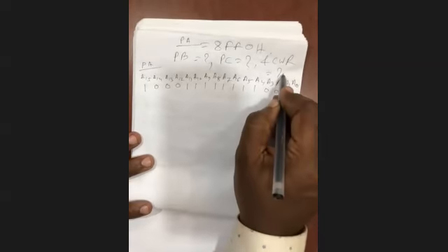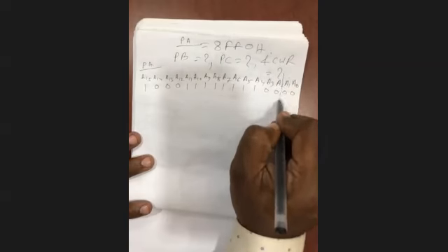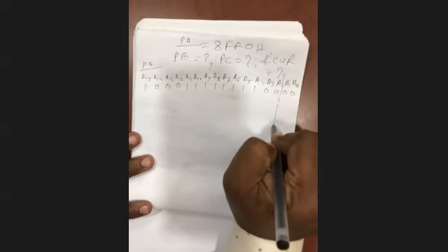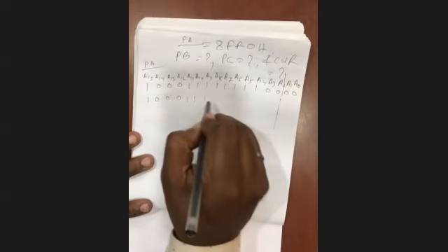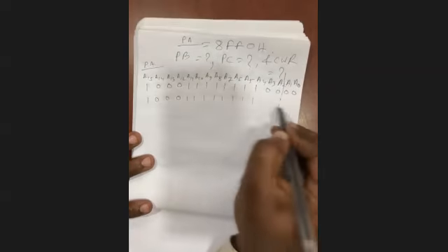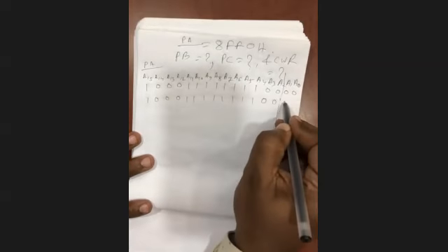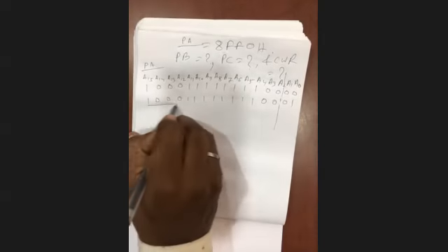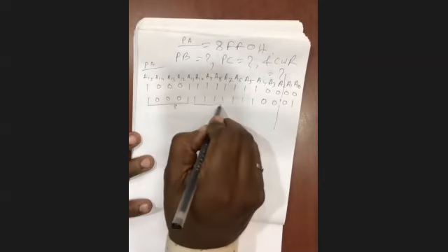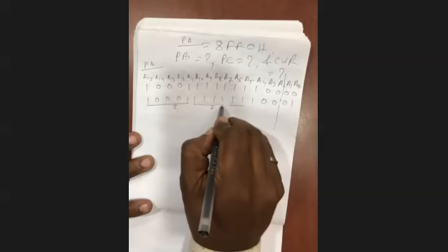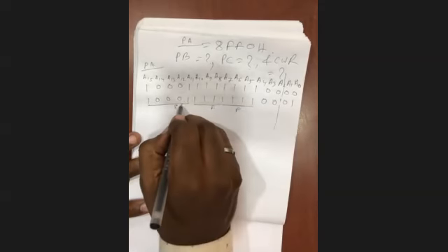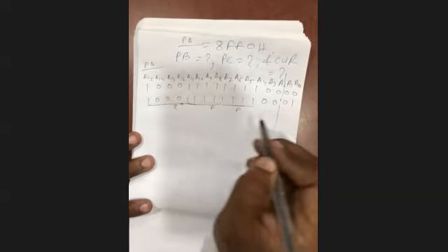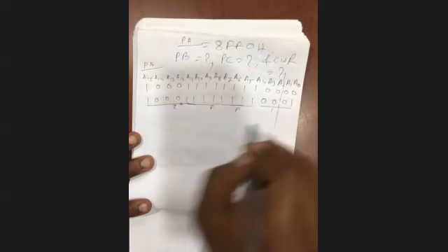So if I'm talking about the port B address, then up to A2 unchanged. So 1, 0, 0, 0, 1, 1, 1, 1, 1, 1, 1, 1, 0, 0. And the last 2 bits will be 0, 1. So what will be the address? 8FF1.